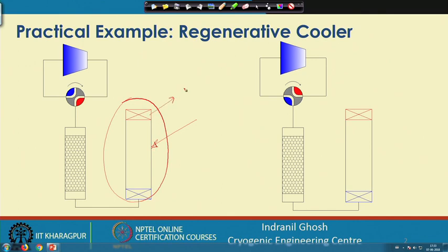Here this is a pulse tube, a thin walled empty tube, and on this side we have a hot end heat exchanger, and on the other side we have another, the cold end exchanger. This is periodically pressurized and depressurized with gaseous helium.